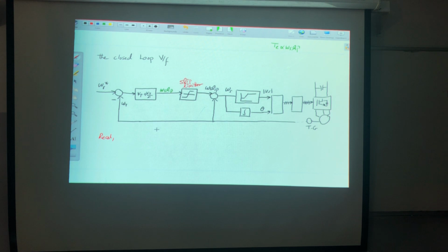Now, if we recall, in order to have a constant flux, it requires constant current. Do you remember, when we derived the relation for the flux, we said the flux in the gap is equal to the voltage across the gap over Xm, correct? And this is equal to E over 2 pi F Lm, and this was Im, the magnetizing current.